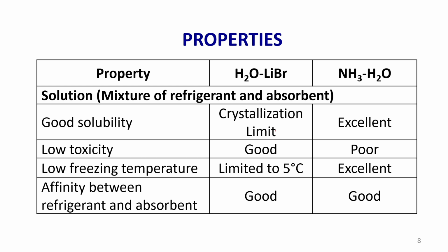So when it is mixed with the refrigerant water, beyond a particular concentration, the crystals start to form, like crystallization. There is no problem if we use that up to a concentration say 50 to 55% or whatever it is, but at very high concentrations the crystallization forms. So the systems would be designed and operated in such a way that the crystallization limit is not reached.